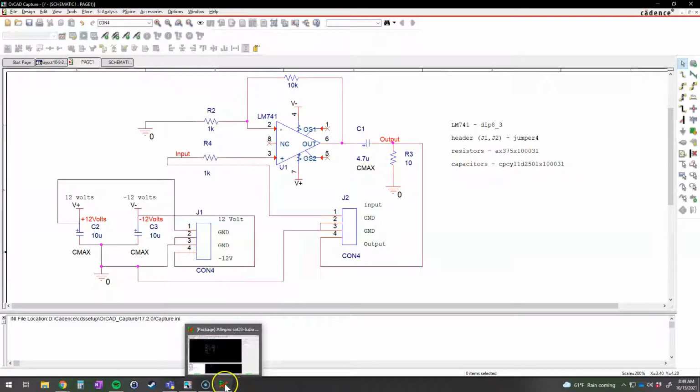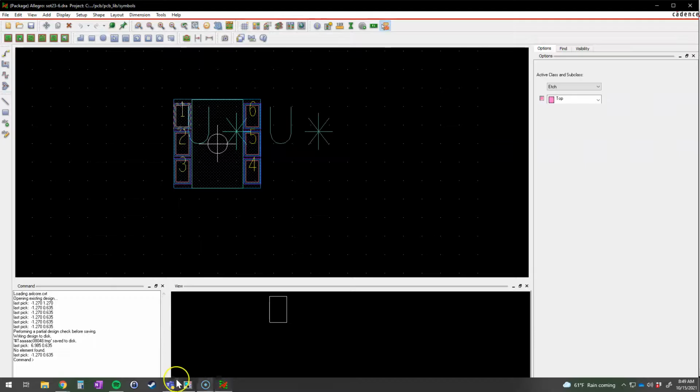All right, well then we're ready to actually launch the PCB editor, and I already had it launched here. Actually, this component that I was working on is an old one, and it has pins that are in the wrong orientation. This is supposed to be like an SOIC chip where these pins should be rotated 90 degrees.